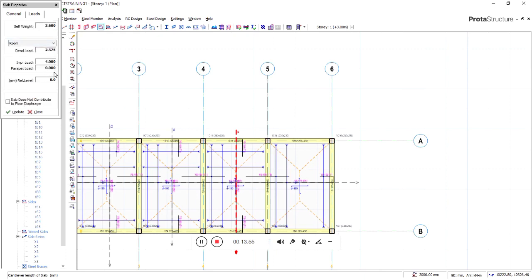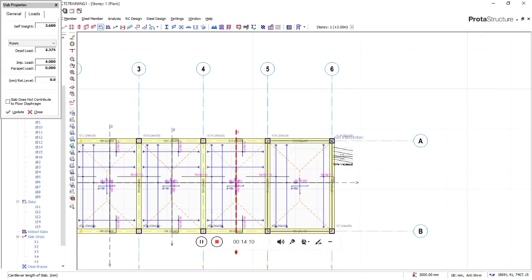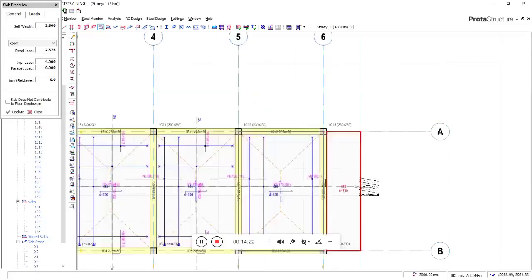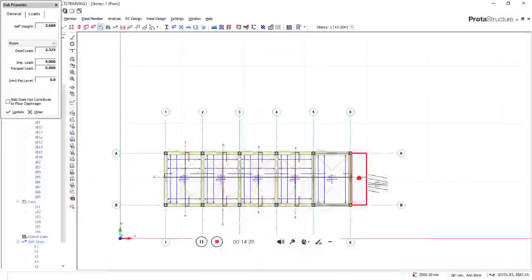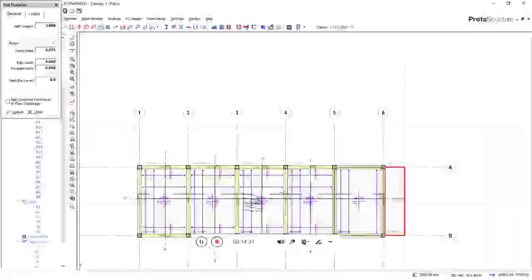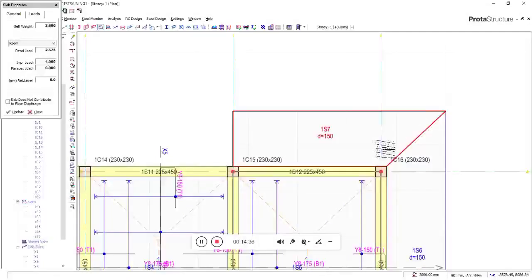And most times the imposed load you don't have to put at this end, just the block wall load. Let me see on this cantilever drawing here. You click on the start point and the end point, and then you can see it's showing you where to put the slab. So you click outside the side you want the cantilever to be. This is the cantilever slab, but we'll not put it here because we have done the slab strip in this direction. For this direction, let's put it here.